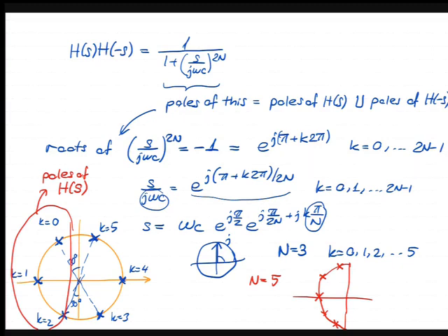The more you put, the higher n you choose, the more poles you'll have, therefore a higher order transfer function. Its implementation will be more complicated, of course, right? You'll have a lot of RC circuits and so on, right? Yes? When you played with these Werkstatt modules, there was a circuit diagram that Alex showed you. That was a low-pass filter. It's like a ladder of RC circuits, right? That was basically a low-pass filter. So it is implementing some kind of low-pass filter.